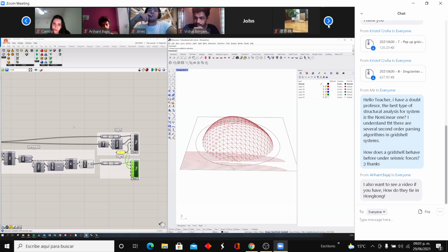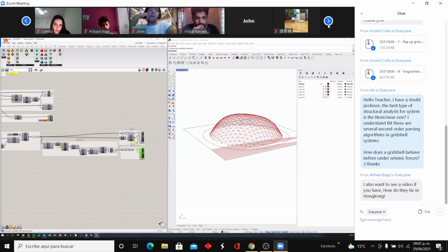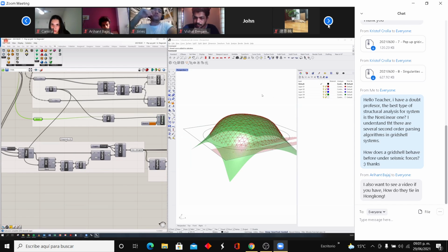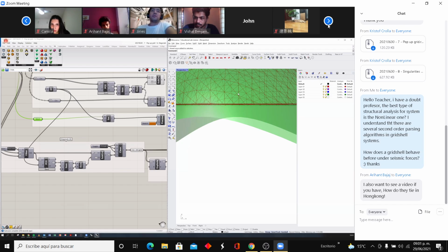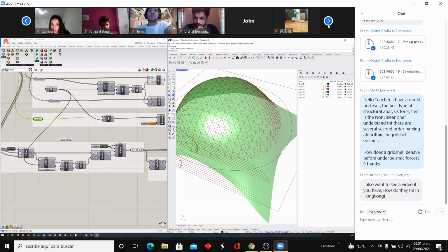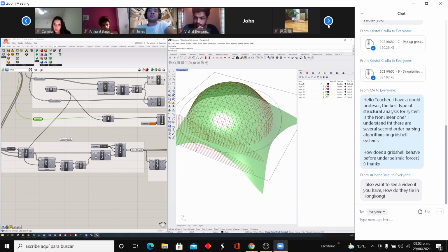It's pretty straightforward because we have the mesh over here, which means that we have the mesh normals, which means that we know exactly how to move things up and down in which direction. So we can just take our original curves and move the points according to the normal direction with first one column diameter and then another column diameter, and then we'd be good. Actually, let me see how fast we go today towards the end of the morning. Maybe we can add that offset thing. I have it done for the singularities because that's a bit more tricky and complex, but for this one, it's actually very straightforward.